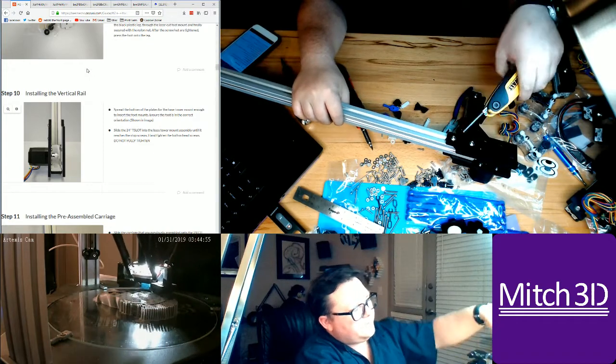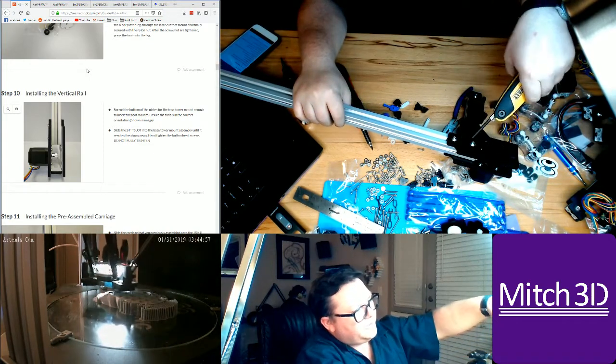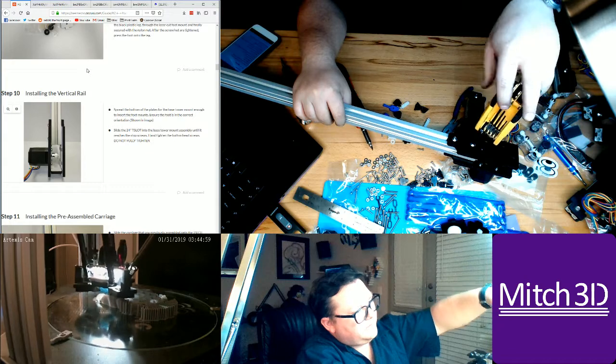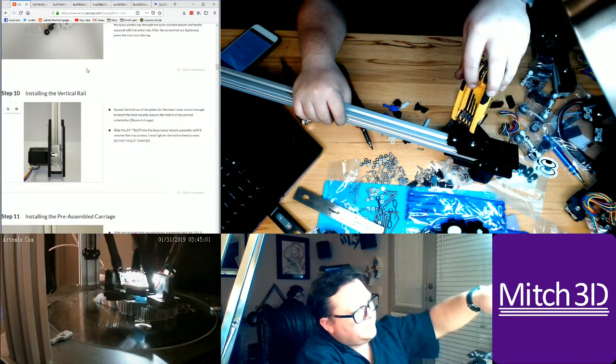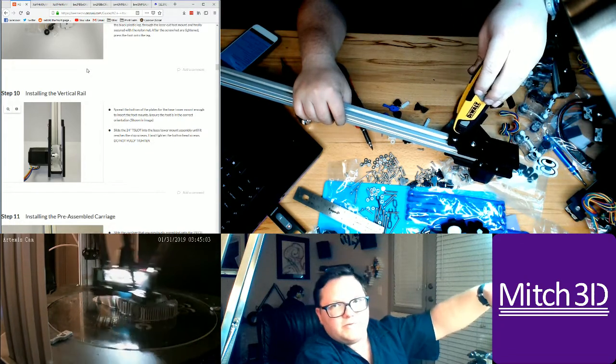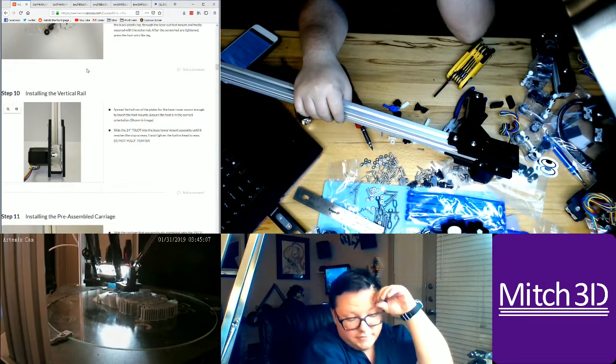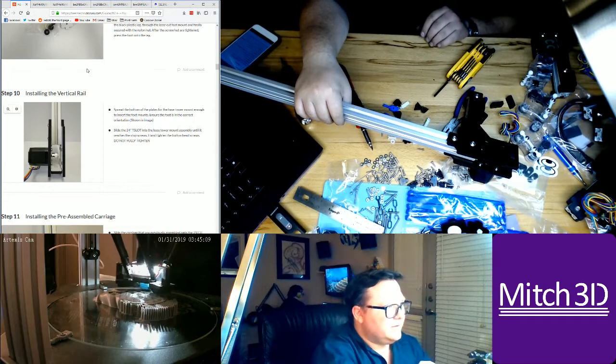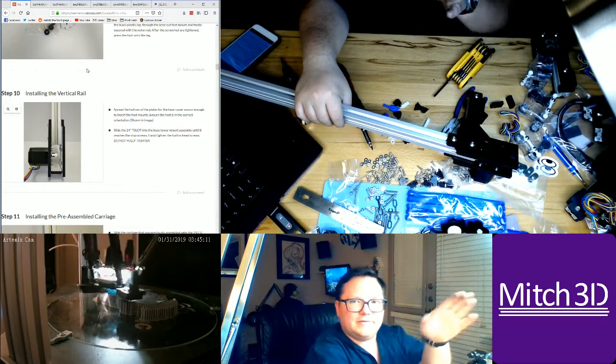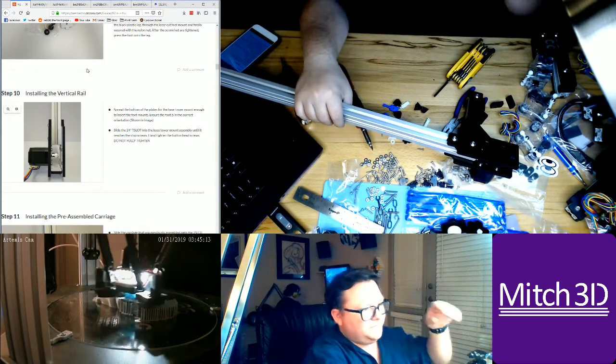And there's a lot of wiggle room, so again, make sure that your top and bottom are square. The problem is that the towers have to be parallel to each other for the arms to work, or all your parts are going to be skewed in that direction.